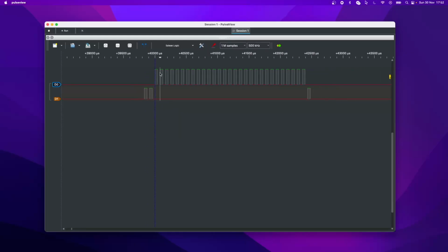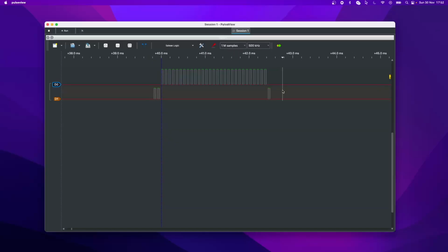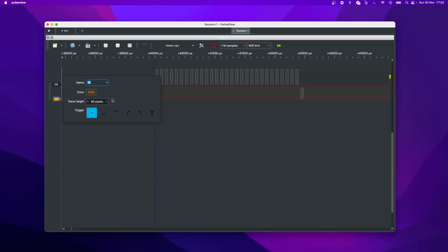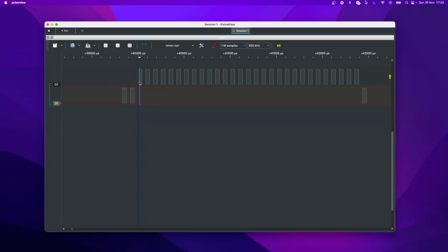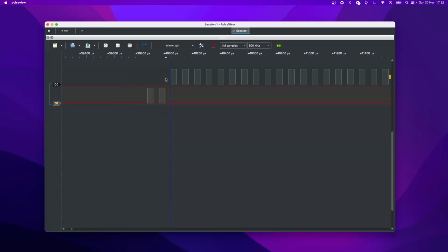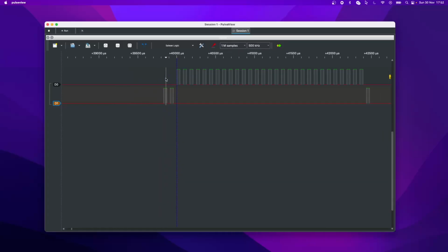As you can see here, that's apparently the first stream of data sent by the ACP, and we can clearly see, let me raise this a little bit to 70, yes, we can clearly see that the acquisition works because we have the differential signal. One important thing I didn't tell you before is that the logic analyzer I'm using can detect only positive signals. So here we are detecting only positive signals from the A and B differential line.